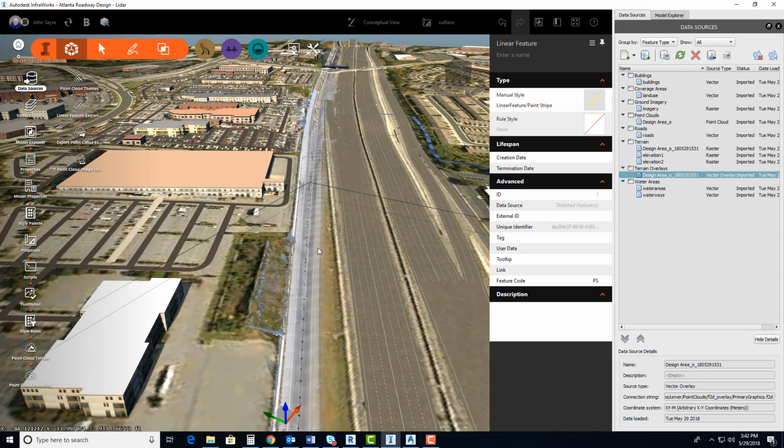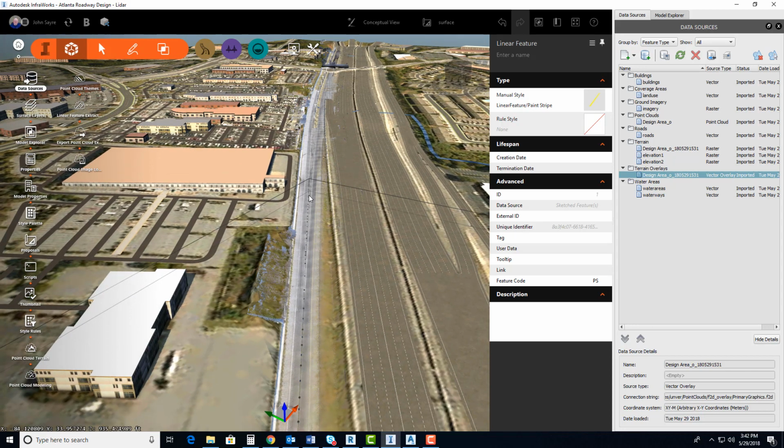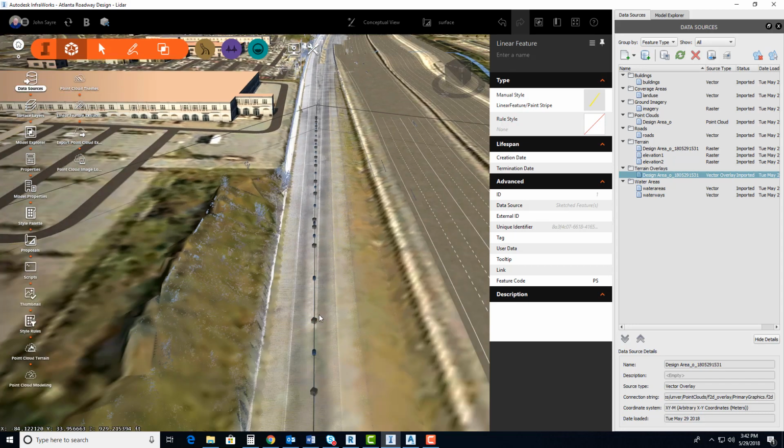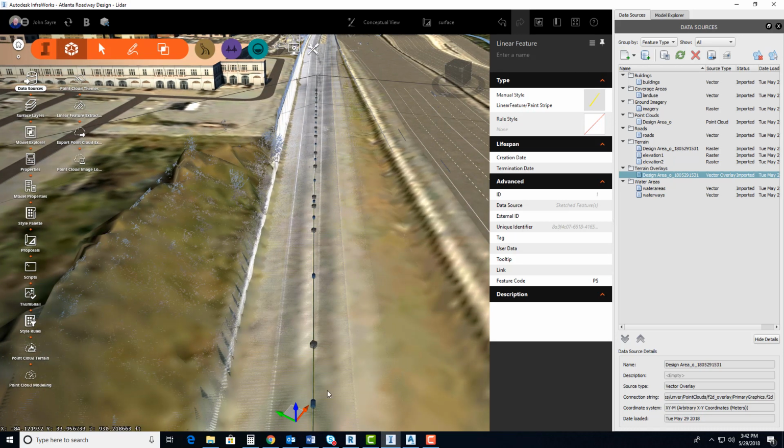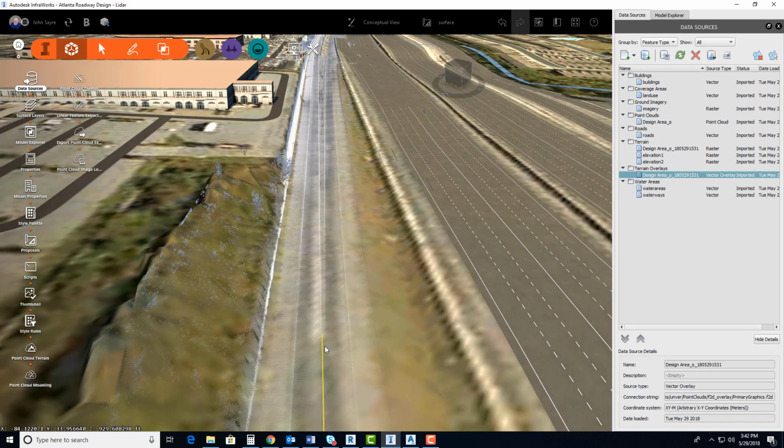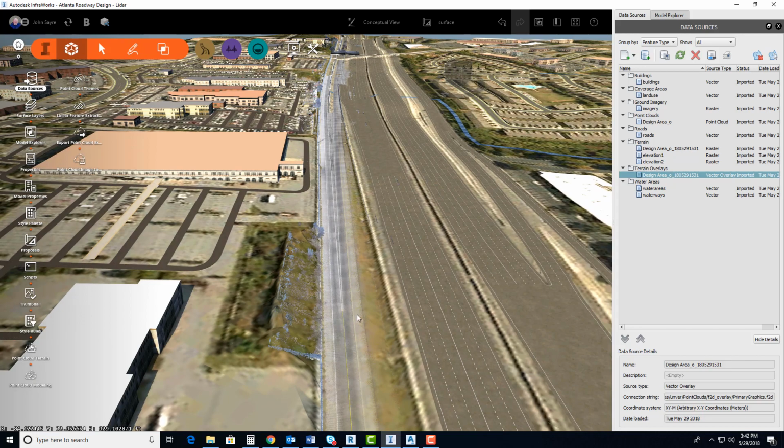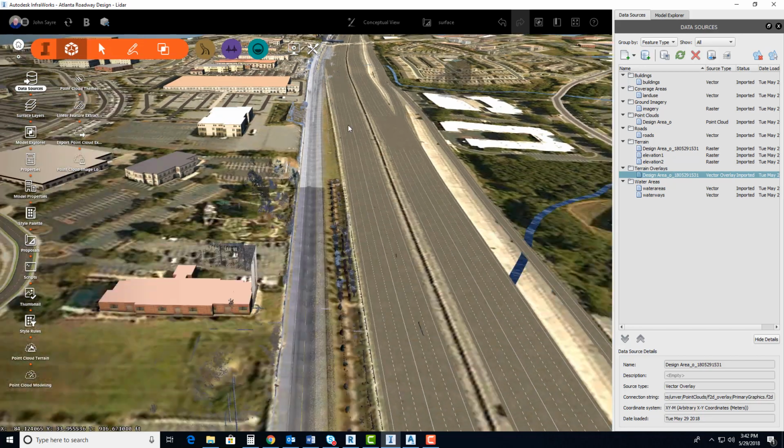We're not concerned, at this particular time, that it goes that far, because we're going to stop it right in this area where the lanes start to divide. So if I want to, I can actually select the linear feature here. I can right click and I can select that I want to split this feature. All right. Then if you see, if I select the feature after that point, it's like it broke it. It's like using an AutoCAD break command. So I can just grab that top linear feature and I can hit delete, and this is where I'll stop my particular generation for this job.